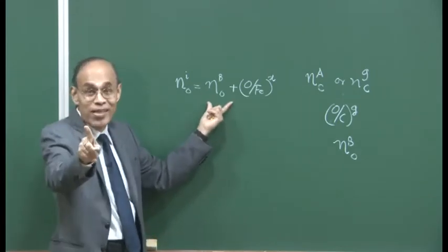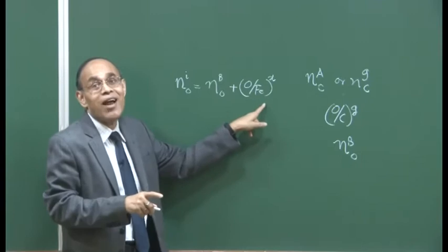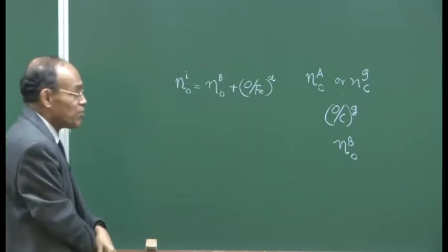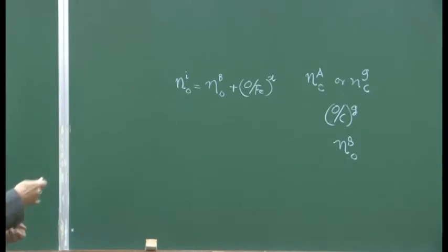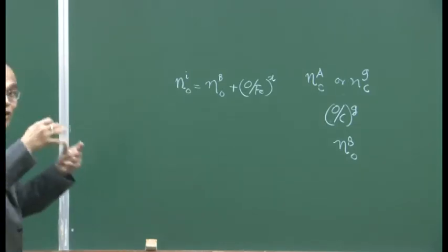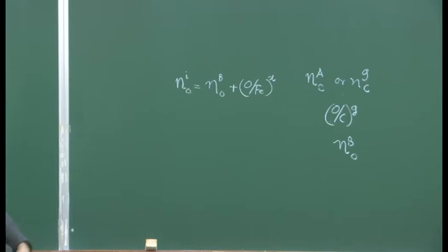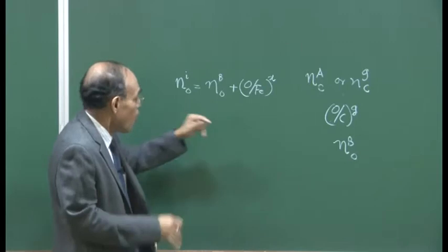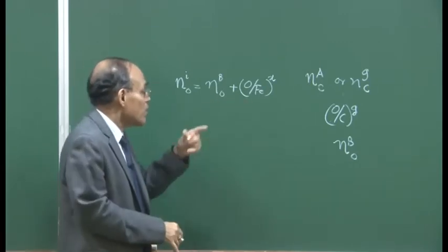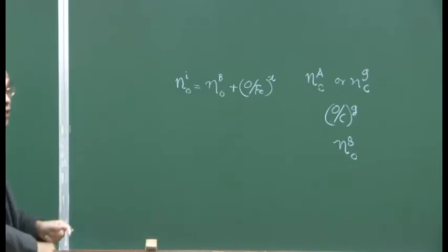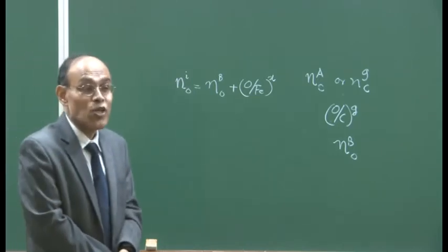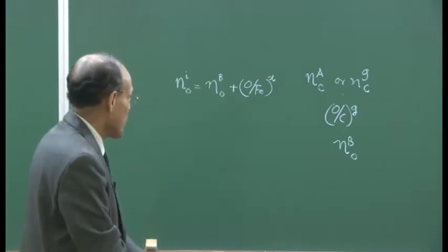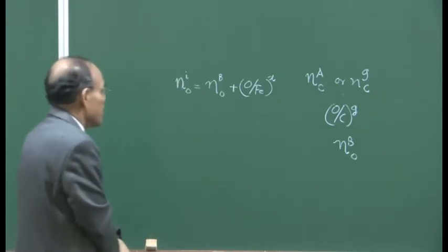But in a real blast furnace, we will have additional terms on top of these 2 terms which I have listed. That you must remember, and we will see, as we advance and make our simplified model adaptable to actual blast furnace operation, how these components can be added to the oxygen input, carbon input, and so on and so forth. For example, limestone dissociation will contribute to carbon production in the blast furnace, or be a source of carbon, because carbon dioxide will be coming through it. So, similar concepts can be applied.